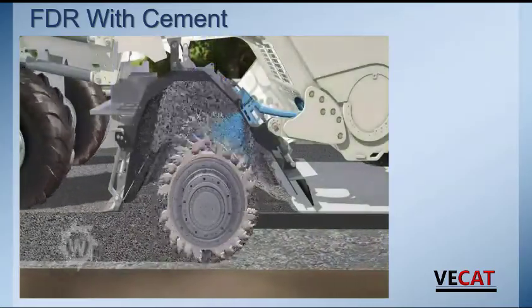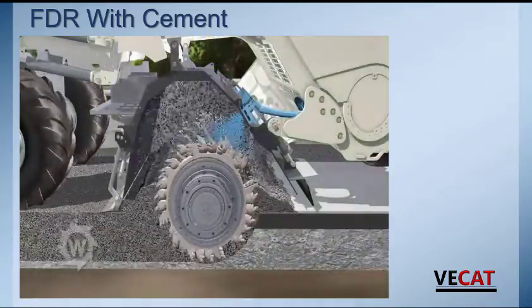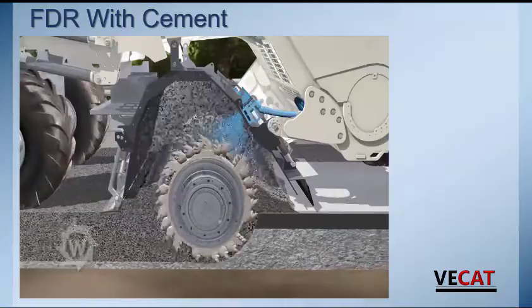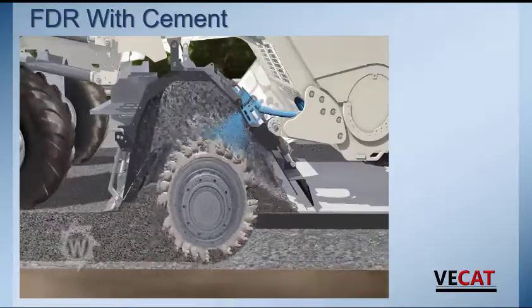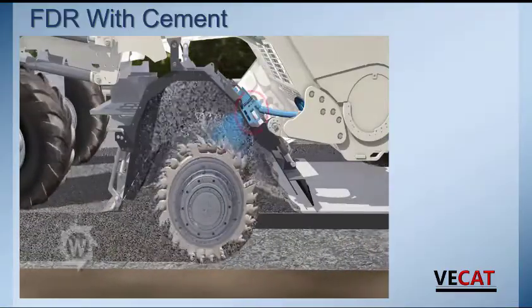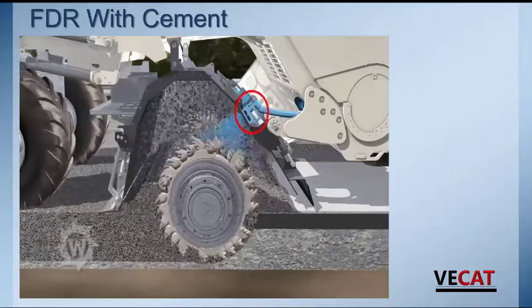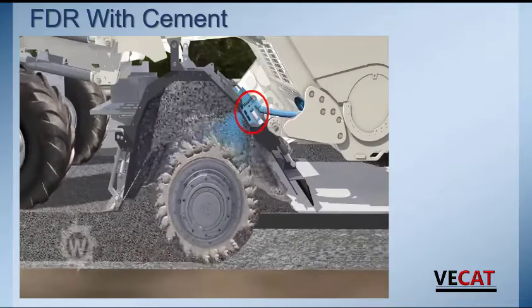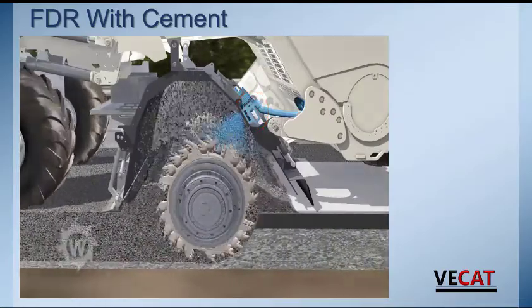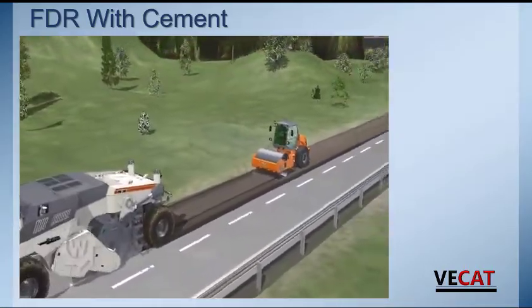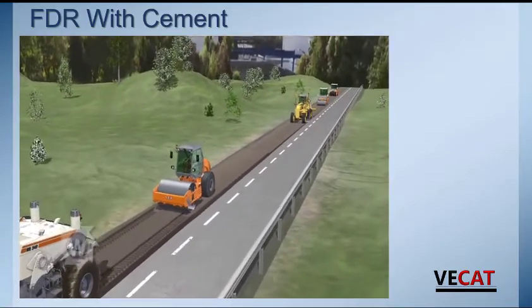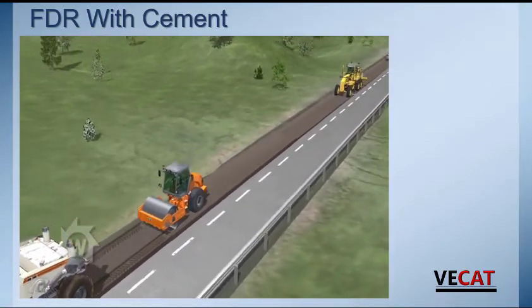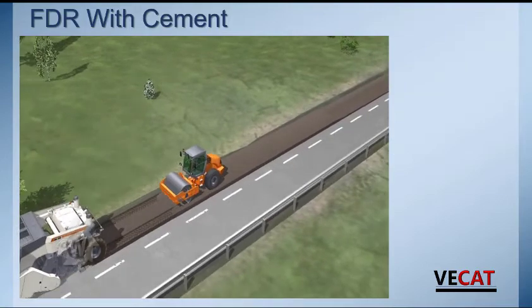The water is injected directly into the mixing chamber to achieve optimum moisture through the entire thickness of the layer, according to the requirements of the mix design. The injection bar is adjustable through 8 individually controlled nozzles to achieve half passes and partial passes. Next, a pad foot roller of adequate size to achieve full density through the entire layer.